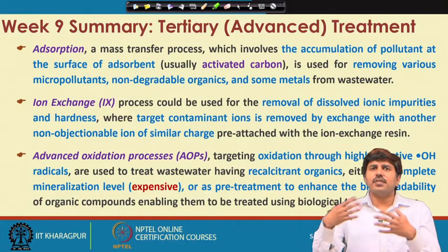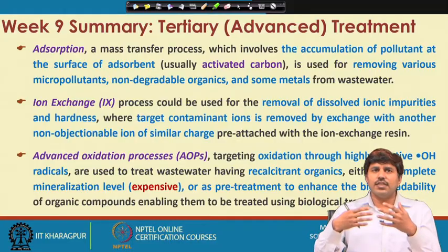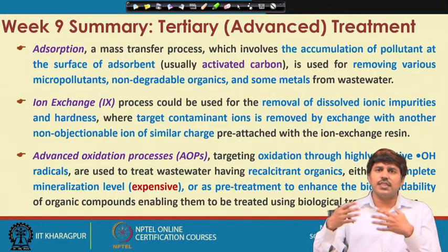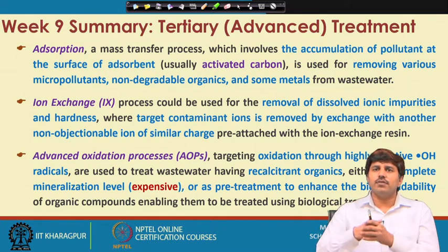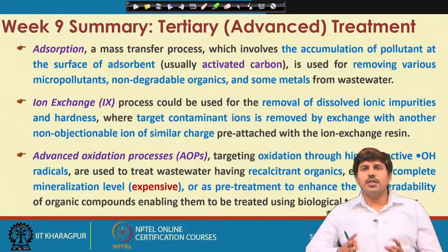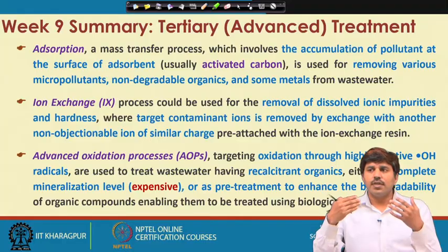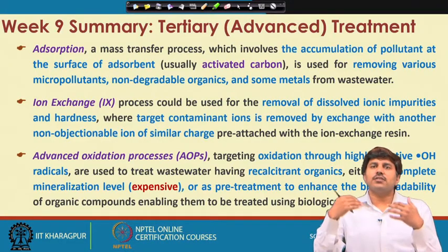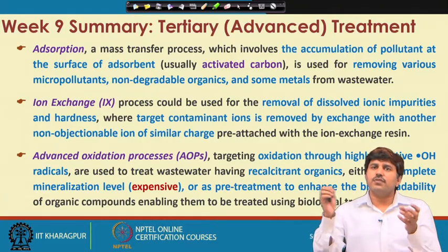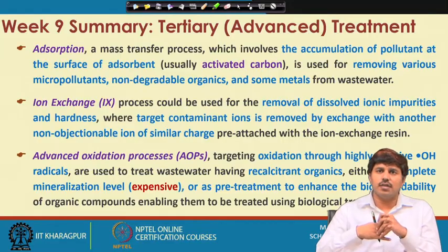Both ion exchange and adsorption have certain limitations, like their capacity can get exhausted. So, they need to be regenerated, and how many cycles we are going to regenerate, all those things come into play. And then there are issues with interfering ions or interfering agents. So, if there are such things which preferentially get adsorbed over the target ion, then the efficiency of these systems will decrease.